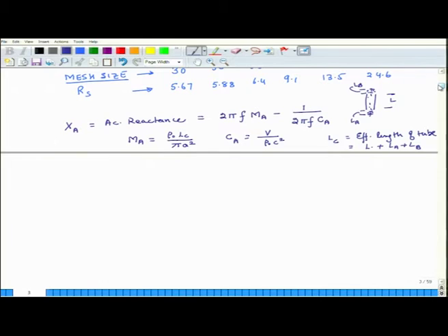And we had also finally discussed how to find L A. If there is a flanged end, for each flanged end we can say L A or L B equals 8 A over 3 pi, and if there is no flange, then L A or L B equals 0.613 A.